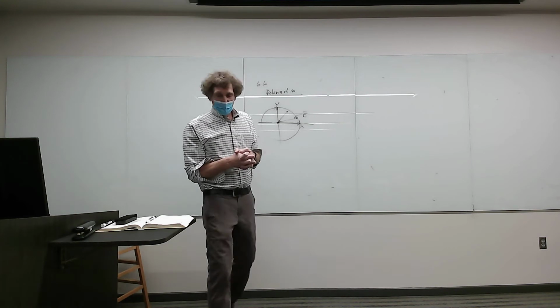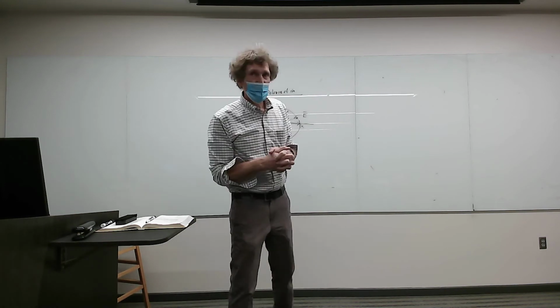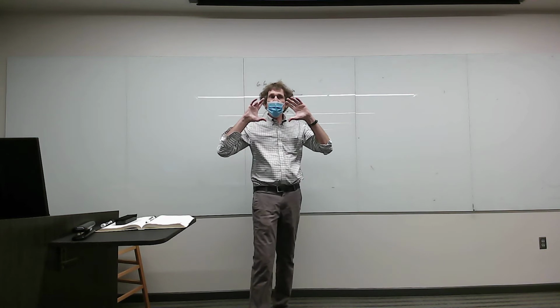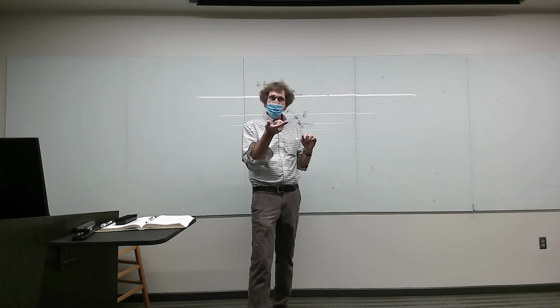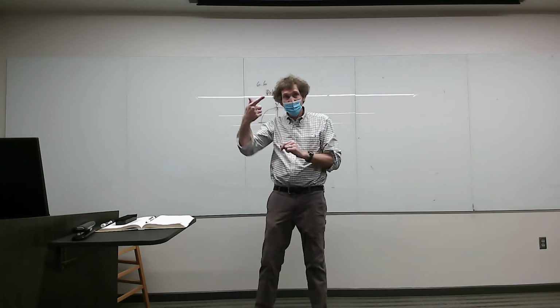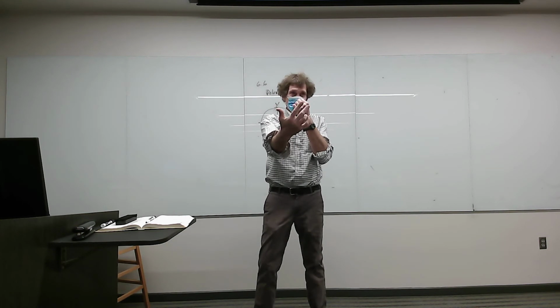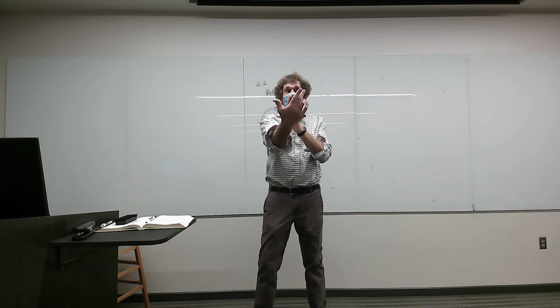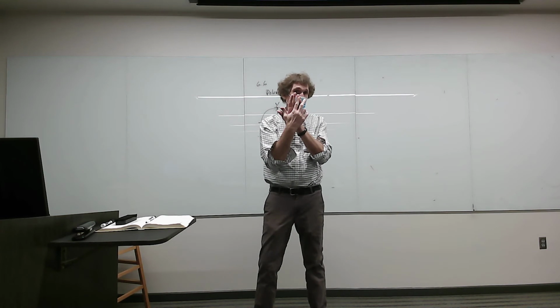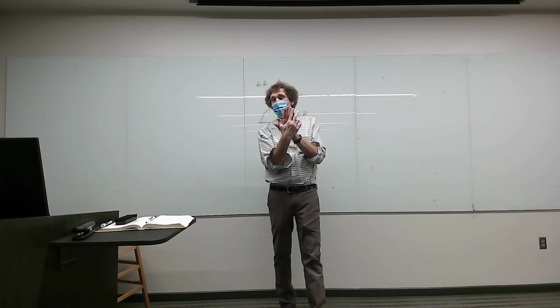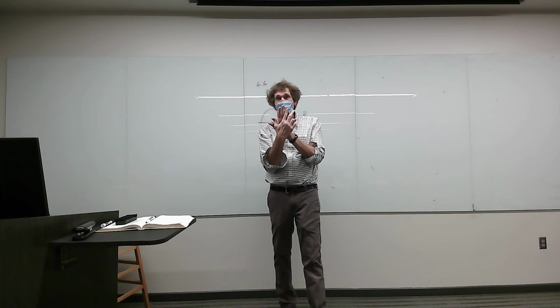And I do radar work. When you have radar, if you put out a right circularly polarized wave, so it's going like this, and it strikes a target, this is a conducting target, it would generate a left-hand circular polarized wave coming back at you. You all follow me? Now that makes discrimination of what I sent very easy.